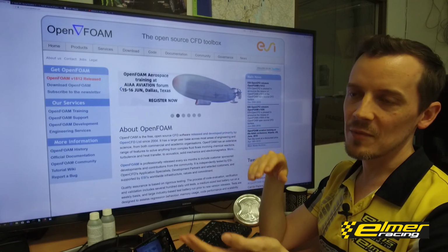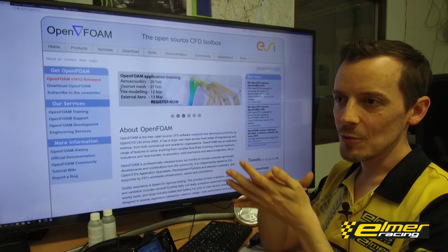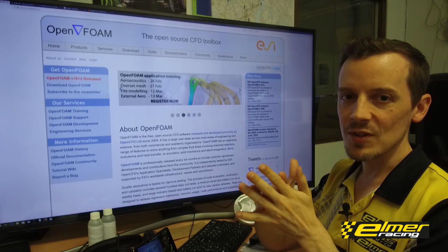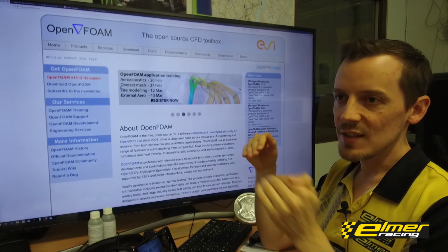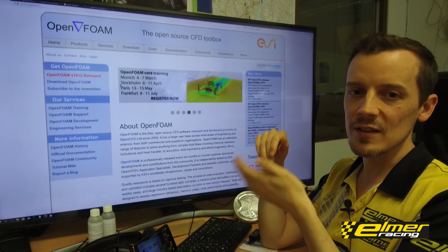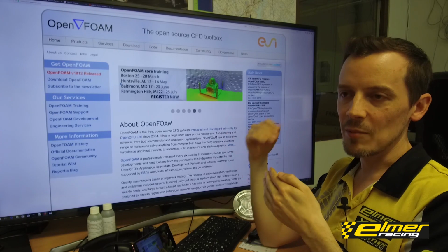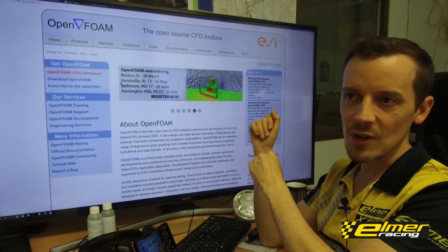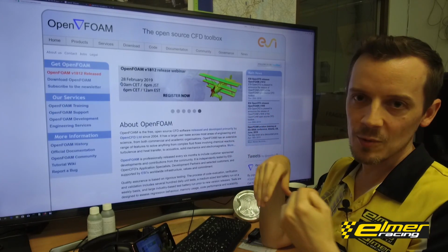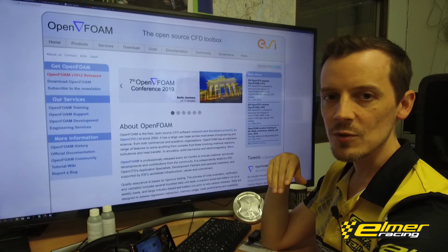Of course, you still get some force values out of that, but they have no correlation at all with real world stuff anymore. So if you change the angle on some wing, but the flow field is completely different in the simulation from what it is in the real world, then the end result will be completely different. You might end up increasing rear downforce when in reality you would decrease rear downforce or something like this, and then the simulations are not very useful anymore.